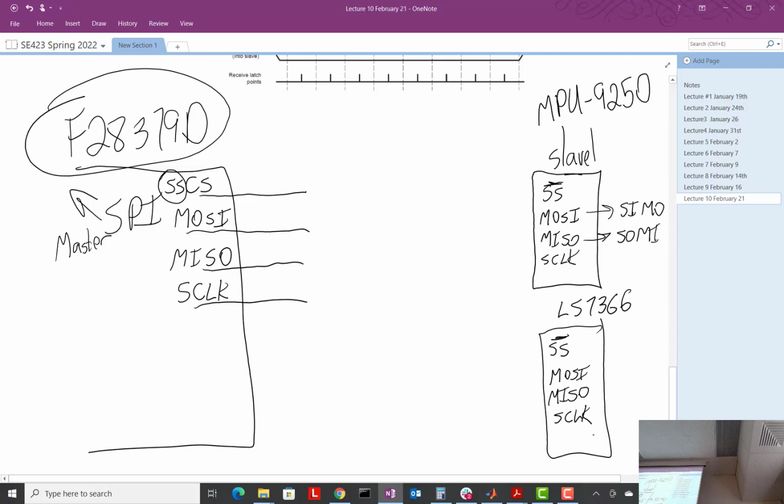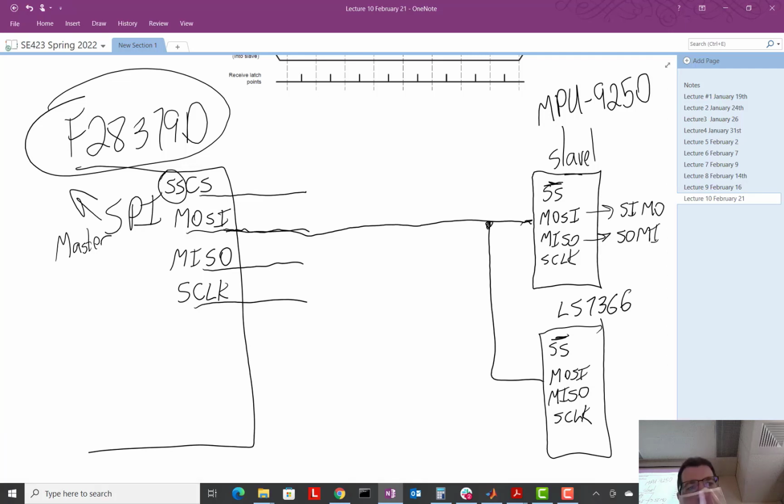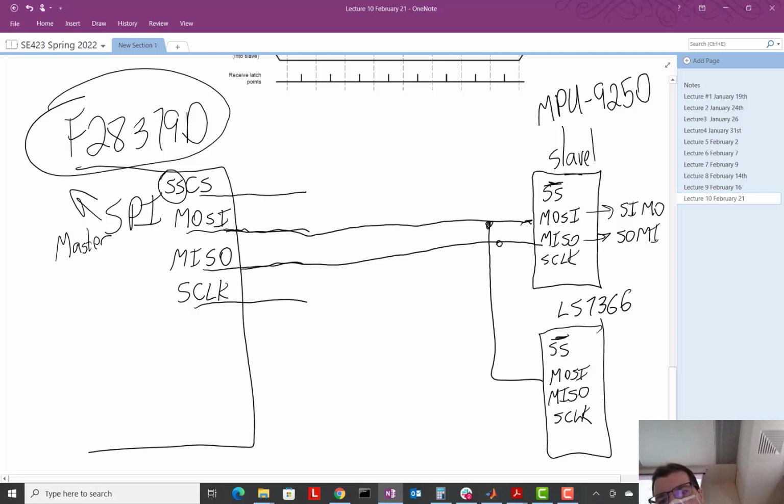Okay, and now the wiring of this. I mean, we could have 4 or 5 chips out there on this same serial port if we want to. So the wiring is actually very simple. We just take the master out, slave in pin, and daisy chain it, or just take it down and connect to those chips. All their master out, slave in pins. Well, they only have one. And then the master in, slave out, daisy chain down to there, and the same with the S clock.